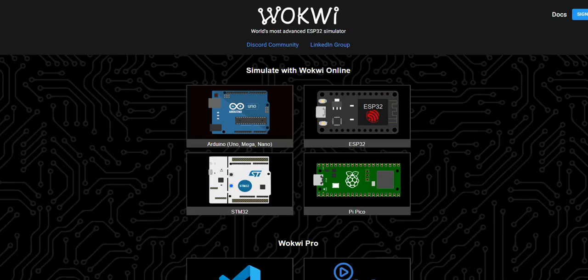Now let's walk through how an Arduino powered IoT system might work. Imagine you're building a smart irrigation controller. You'd use soil moisture sensors to collect data about the hydration level in different parts of a garden. The Arduino reads the data through its analog input pins. It applies logic to determine whether the soil is too dry. It activates a relay module to power a water pump if needed.